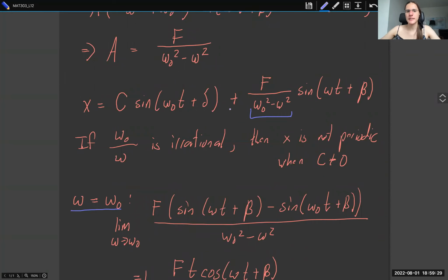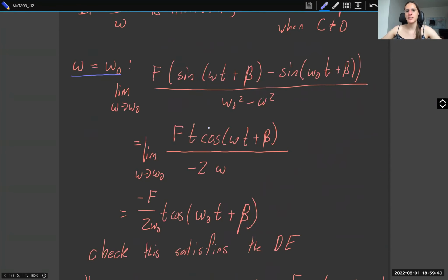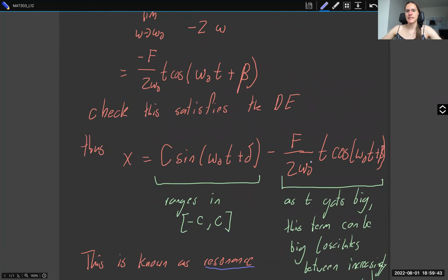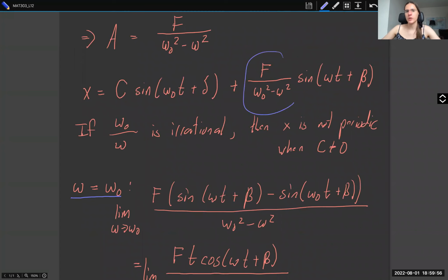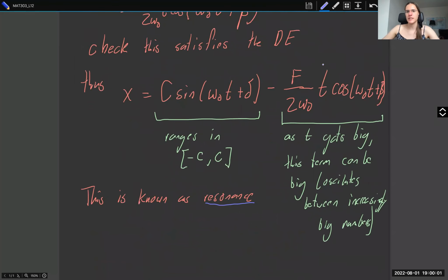So there's going to be some term that just depends on what the initial conditions are. But ignoring that, the closer they march to the resonant frequency, the bigger this term gets, although it's still bounded. But if they march exactly at the resonant frequency, then as time goes on, the vibrations are going to become bigger and bigger, and this is going to cause the bridge to collapse. Because we have an out of control term, whereas here it was just an oscillation, which potentially got big if you got close to the resonant frequency. But when you're exactly at the resonant frequency, this term just blows up with time.